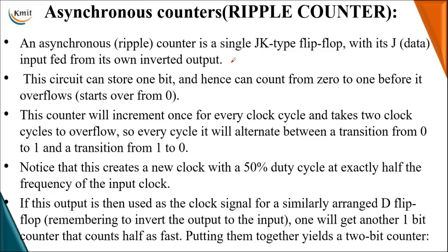Let me write here the binary sequence of a 2-bit counter, which starts with 00. Next is 01, next is 10, then 11. Just observing the first bit position, the initial state has 0, the next state has the least significant bit 1, the third state has the least significant bit 0, and the last state has logical 1.